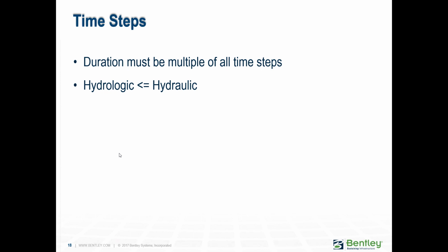Okay, some basic things. The total duration must be a multiple of all time steps. The hydrologic has to be equal to the hydraulic, or it can be less. And then you get to set when you want to report all your results at every single point, which basically uses the lower of the hydrologic or hydraulic. Or you can say, no, I don't care.